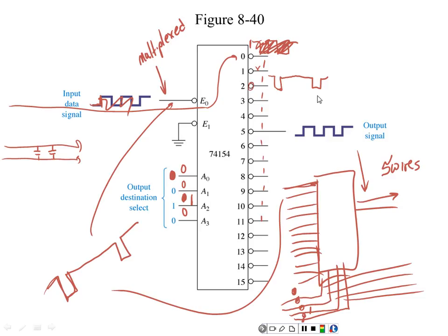We have two types of multiplexing: time domain multiplexing and frequency domain multiplexing. Digital is time domain multiplexing. As soon as you get into frequency domain, you have to get into an analog world, because you need analog to digital converters, and there's a lot more you have to understand about how we modulate the information. Modulate is when we take information and place it on another frequency that we call a carrier. So that's how we modulate it.